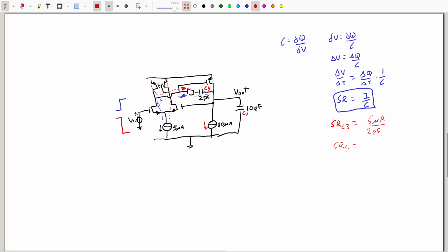In C1 there is this current source, that is the one that is going to be limiting the discharge rate of capacitor 1. This common source transistor will be able to provide charging current depending on how the voltages and currents are in the previous state.